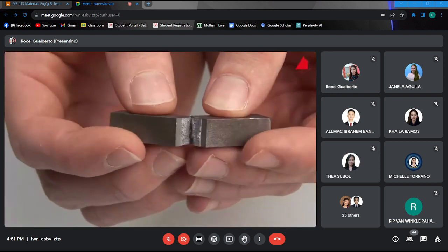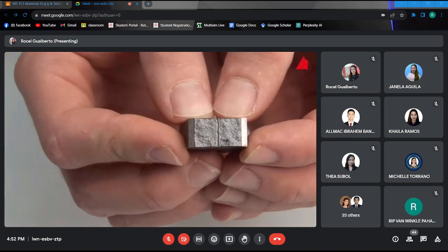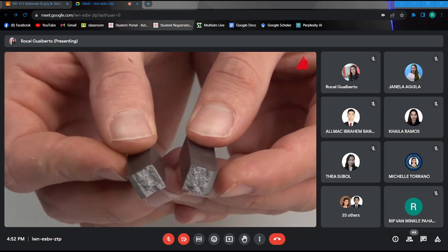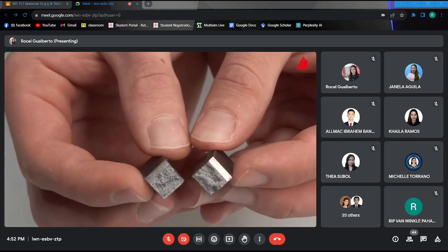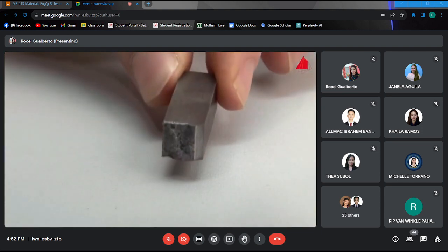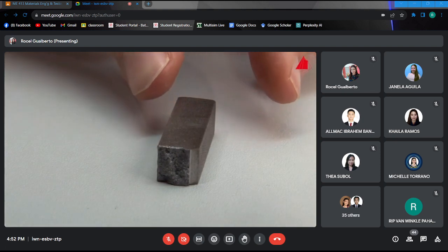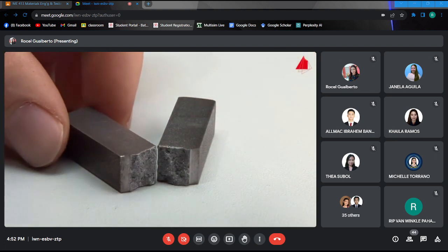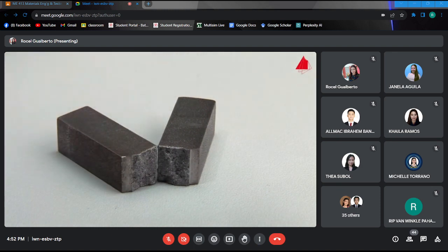The first specimen only shows very little plastic deformation. A mostly flat, slightly glittering fracture surface has been formed. This is another important indication that this kind of steel is only able to absorb small amounts of notch impact energy. It shows mainly brittle behavior due to the strain aging effect.